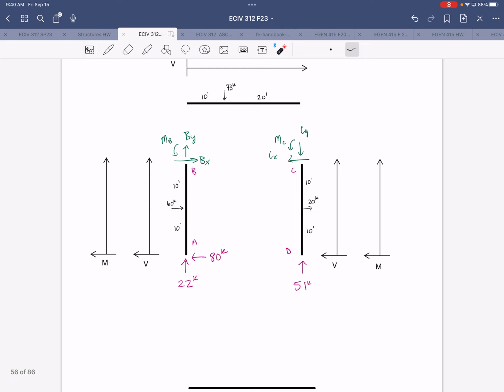And then once we know the actual magnitudes and directions of these forces, we will transfer them to the beam. So they'll be equal in magnitude and opposite in direction on the beam ends. Now you could do that at this point, and write them all out as unknowns.